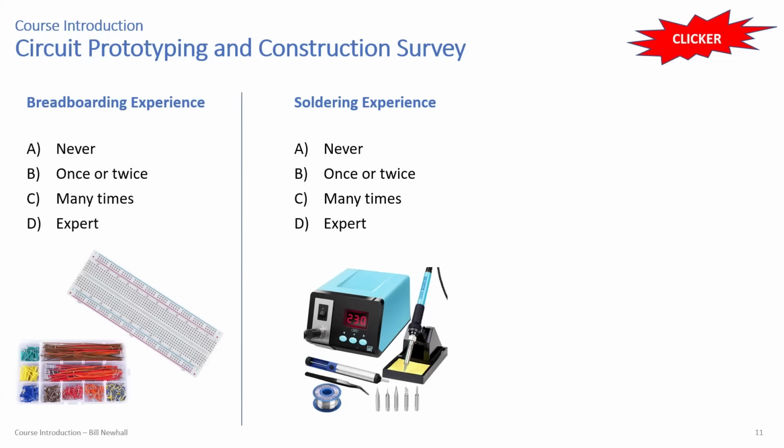It's available. Alternatively, stop by the ITLL, sit down at a soldering iron, grab the staff, and practice there, because you'd rather mess up on someone else's circuit board than your project circuit board. It's good to get some experience soldering, especially when you're trying to troubleshoot a circuit. Desoldering especially can be difficult, but project assembly often requires some kind of soldering.